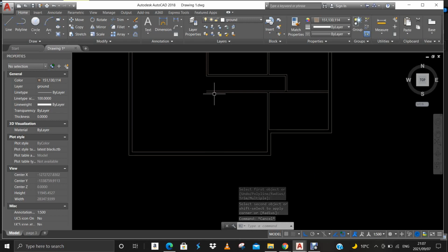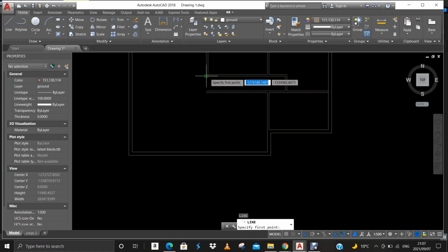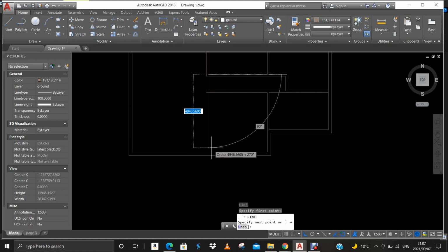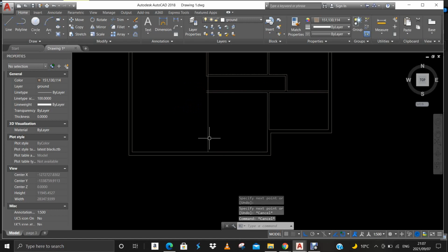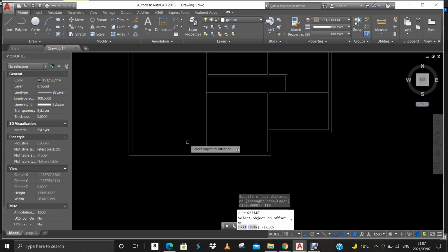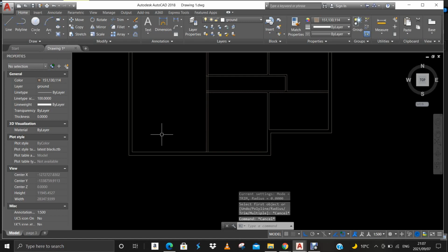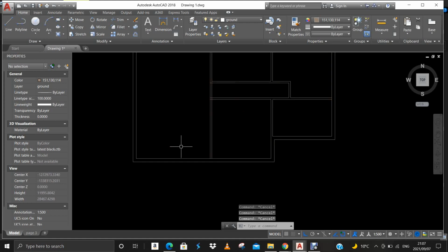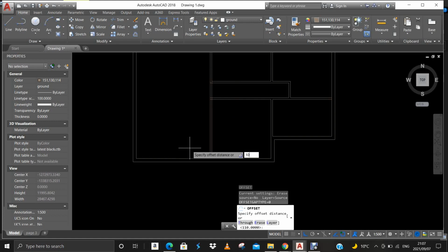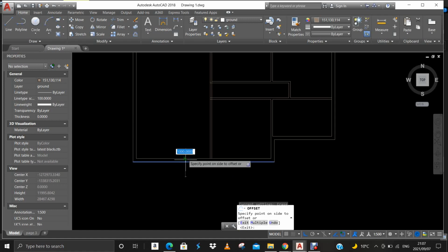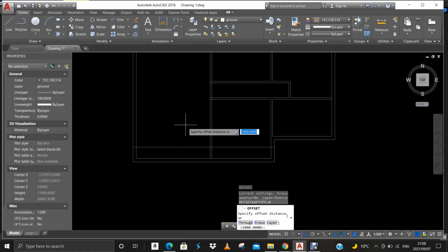So with that being there, I'm gonna offset again, and now I want to have a veranda here so that when you are here you don't get burnt by the sun, or you can chill, something like that. So I'm gonna offset and I'm gonna make the veranda 1 meter from this line. And then I'm gonna offset again and go 220, make my out wall.